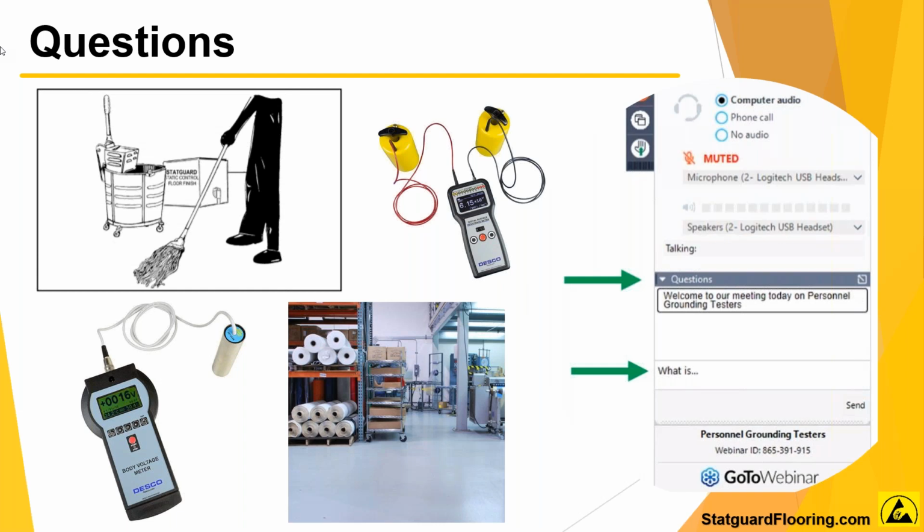There was a question: is Freestyle any better in terms of resistance or ESD performance than the standard tiles? No, it utilizes the same top sheet, which is our 8400 series. The interlocking bottom is very conductive, in the 10^3 ohms range. So is the conductive 2-part adhesive. The only difference in the two installations would be the bottom interlocking base or the conductive adhesive, which are both 10^3. So the resistance of the tile would not differ between Freestyle or a glue down option. It's the same product.